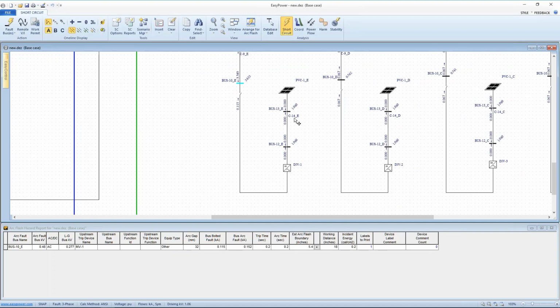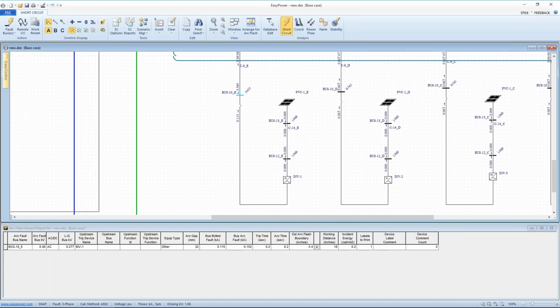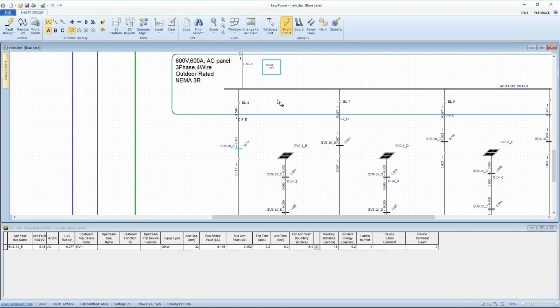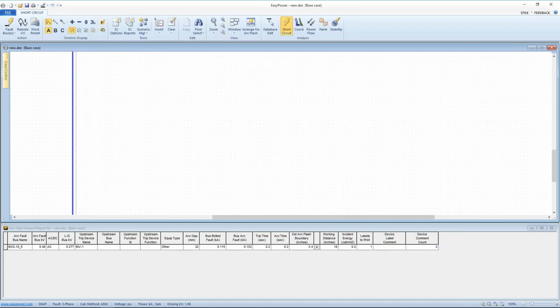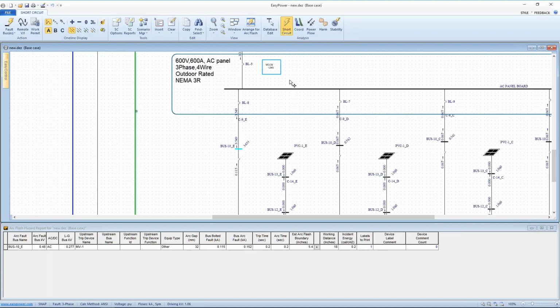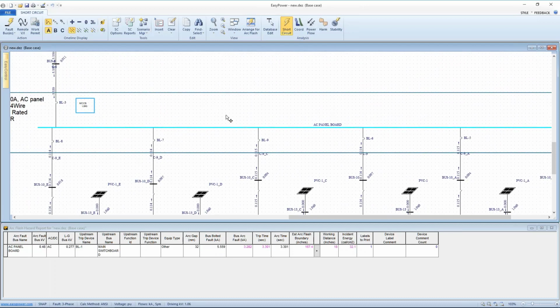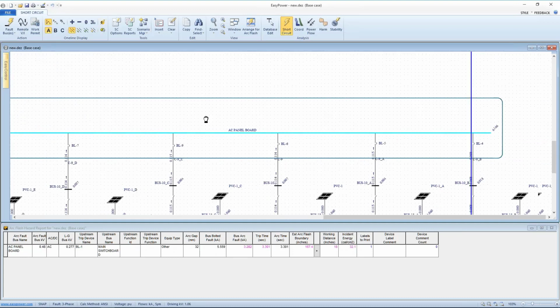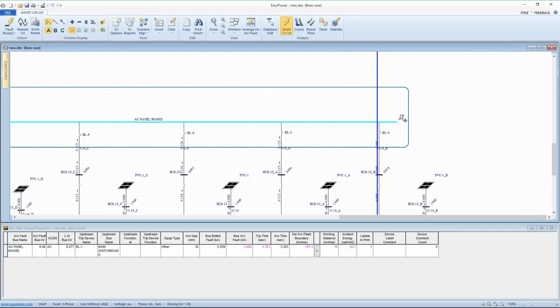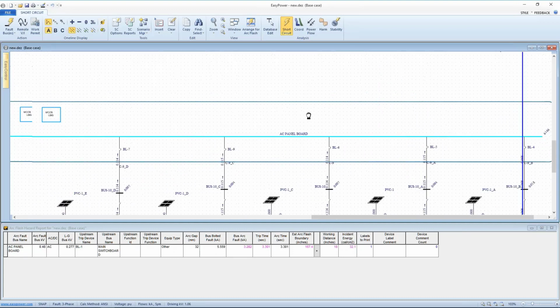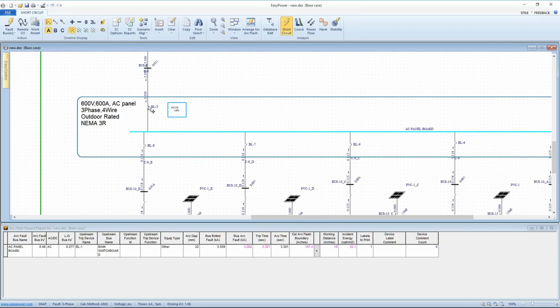somewhat artificial, and it will vary, depends upon what the manufacturer's data sheet says. But the question is, do we have adequate protection when it comes to this collector bus or this totalizer bus being summed up? It's going to see a total of 6,000 amps, most of which is coming from the utility.